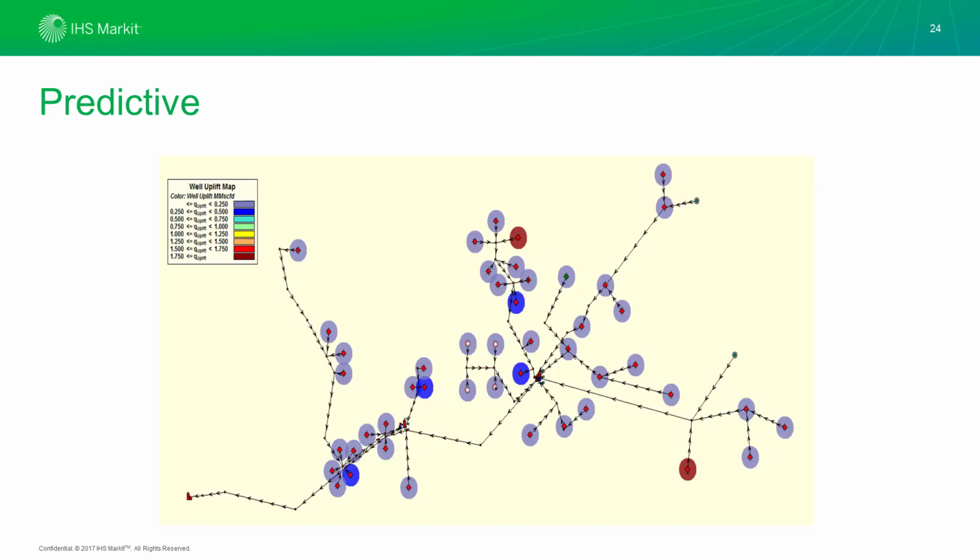This is the well uplift map, and it shows the difference between our absolute open flow conditions at this point in time and our current operating rate. So right away, we can pinpoint where there is remaining potential. The light colored wells indicate there is less than 0.25 million standard cubic feet remaining between the absolute open flow and current operating conditions.